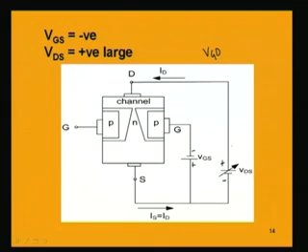So, what will happen is that if we go on increasing VDS, a point will be reached when the N channel will be having only a point of touch at the drain side. It will be almost like it will be touching at the drain side. When this happens, it is also like a pinching off phenomenon, that there will be saturation of the drain current.